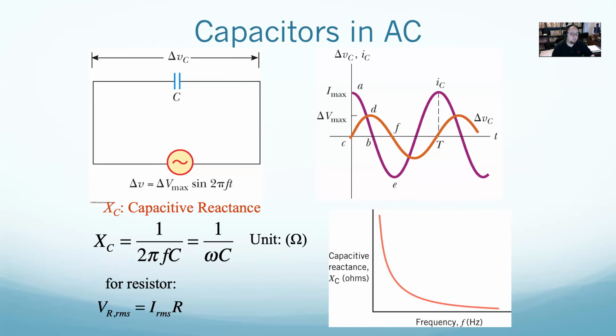Now we know for a resistor, V equals IR. And here's the thing, for a capacitor, that will work. The voltage over any capacitor will be V equals I X. Well, X is once again the capacitive reactance. And that'll let us find the voltage over any capacitor, given current, or vice versa. More commonly, you know the voltage, you'll want the current.